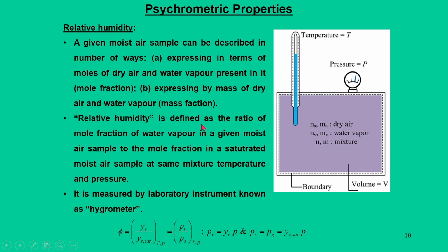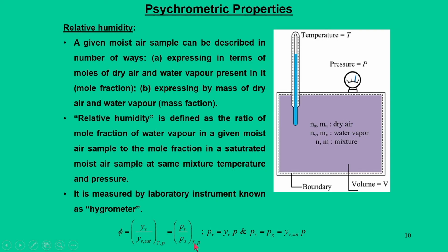Although both numerator and denominator are in kg, since you need to separate out dry air and moist air in the humidity ratio, it is assigned a unit. On the other hand, relative humidity does not have any unit, because it is finally expressed in one unit, bar, and for phi the bar in the numerator and denominator gets cancelled.